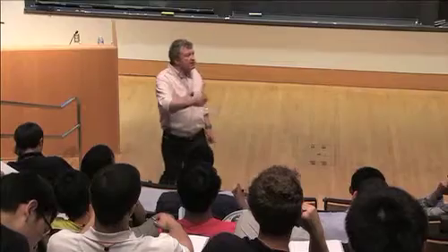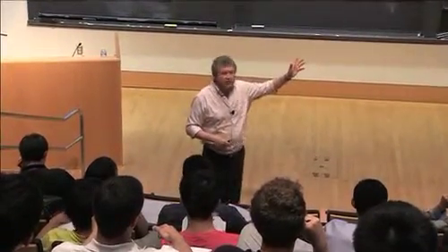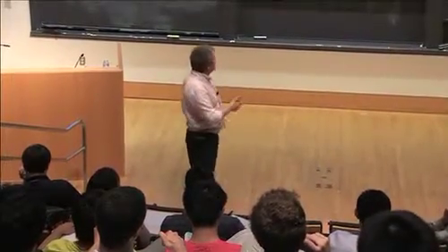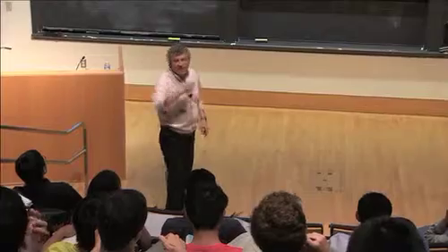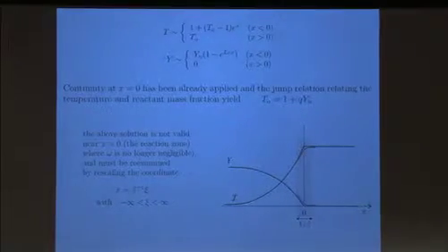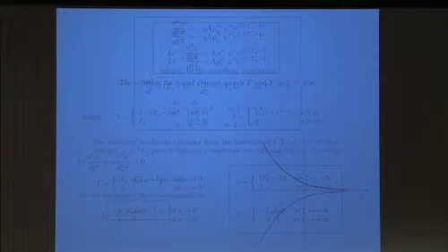So when you read in some places that people say, oh, but the asymptotic solution gives you a flame thickness which is not physical, it's nonsense. The flame thickness is 5 times LF, it's not LF, okay? Remember, there's a factor there. It's just LF, a representative value for the non-dimensionalization.